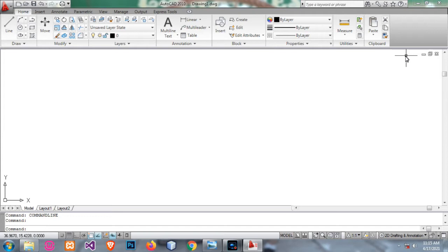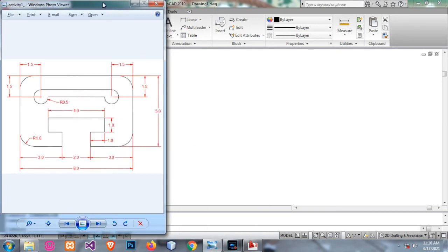To know the exact limits needed, we will make sure that we have these two important pieces of information. First, what AutoCAD unit have you selected? In our part 1, we selected centimeter as our default unit, so we are now using this centimeter AutoCAD unit. Second, what is the longest dimension of your drawing? Let's take this example as our drawing.